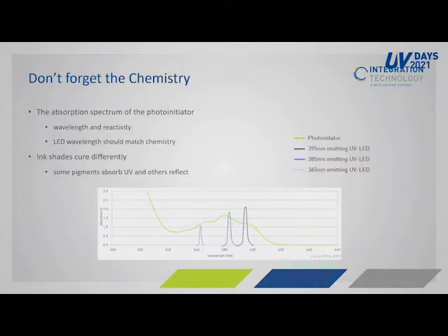And also, last but not least, the chemistry, the formulation. You mustn't forget that side of things. The chemistry has to match the lamp, the wavelength. The photoinitiators need to be the correct photoinitiators for the LED system, or the wavelength that you're using. So that should also be considered.